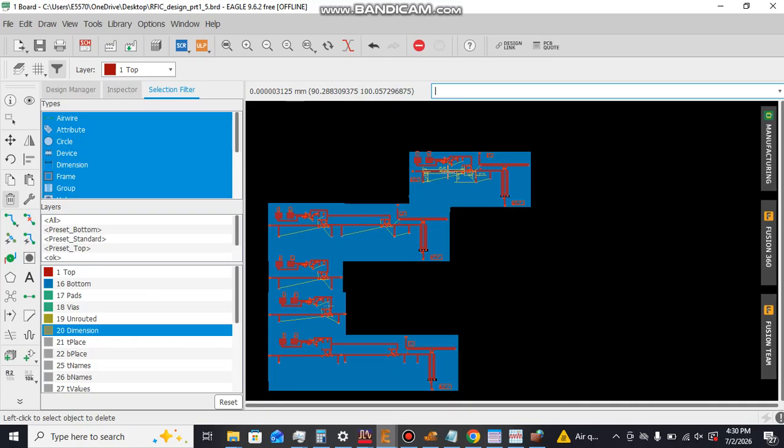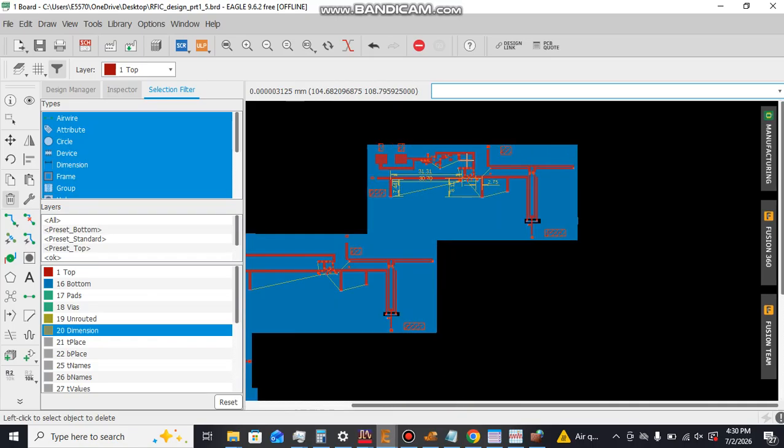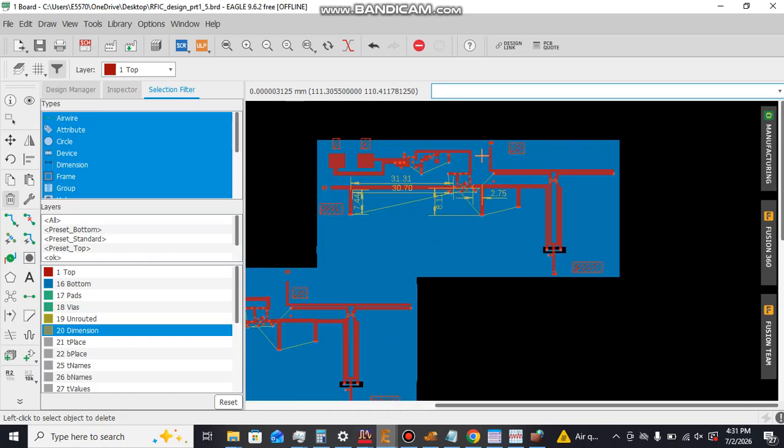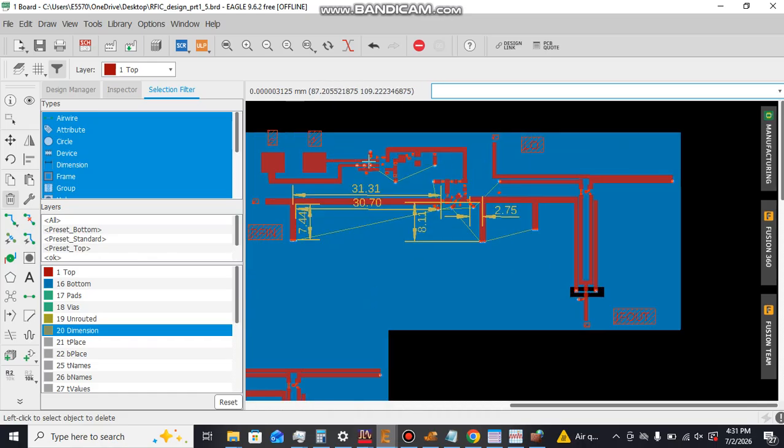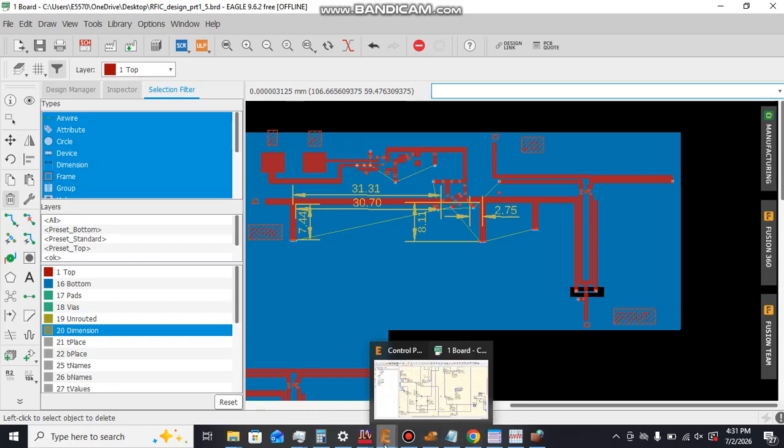There's one improvement that I've done from my last videos. The first thing is that the voltage regulator from my first low noise amplifier was not working, and that was because the voltage regulator was not connected correctly.